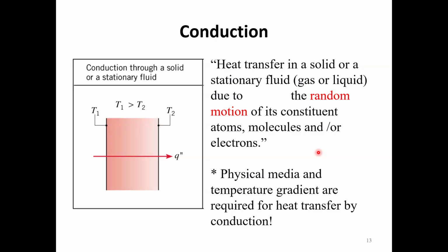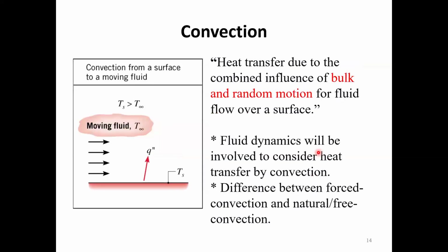A good example would be windows. You have two layers of glass, between which gas is sandwiched, and you can assume that the gas is not moving through that thin gap. Then heat transfer can be assumed to happen via conduction through that non-moving gas, the stationary fluid. So this is heat transfer by conduction.